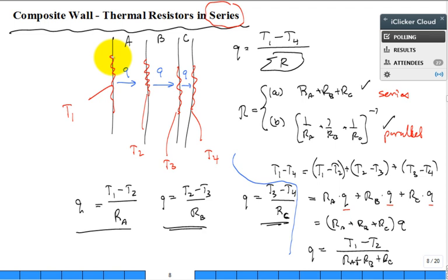When you're establishing a resistive network like this, find where you have temperature nodes. Didn't we talk about everywhere along this face is T1? And then put a node in corresponding to that temperature. Nodes in networks correspond to places where you can get a temperature, like at a surface. And then over here, this is T2. Don't put nodes that represent fluxes. That's confused. Nodes represent temperatures, just like an electric resistive network.